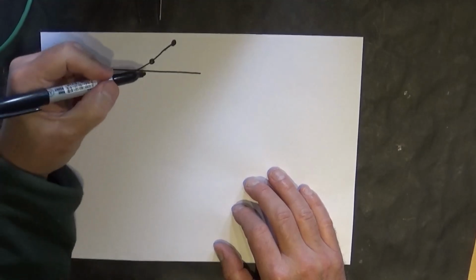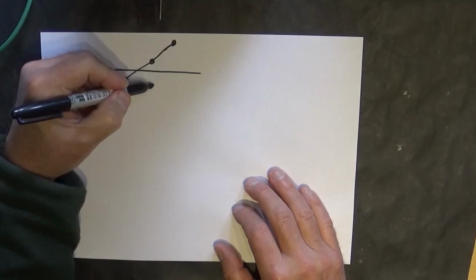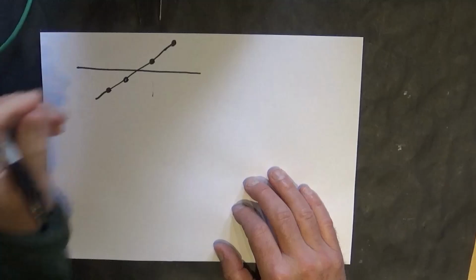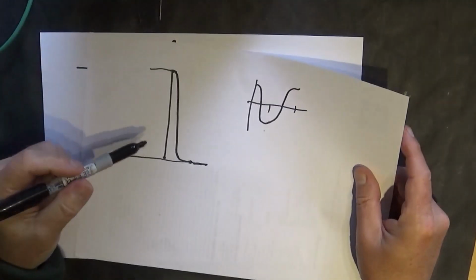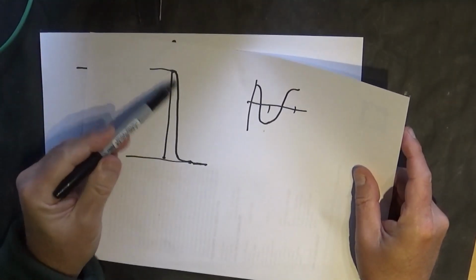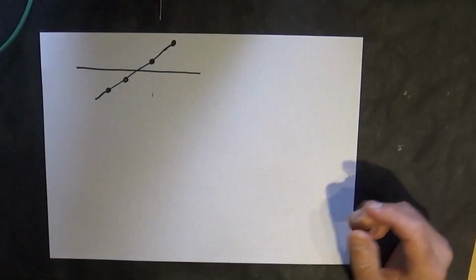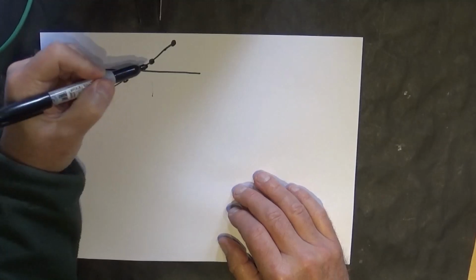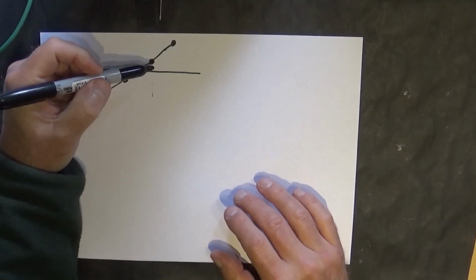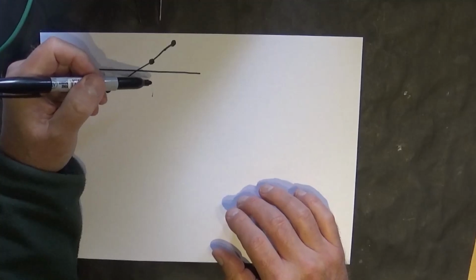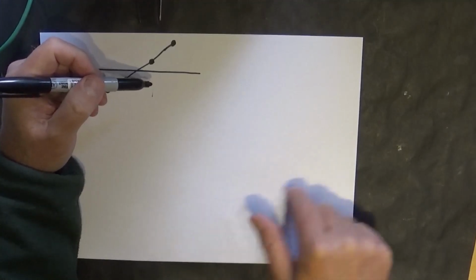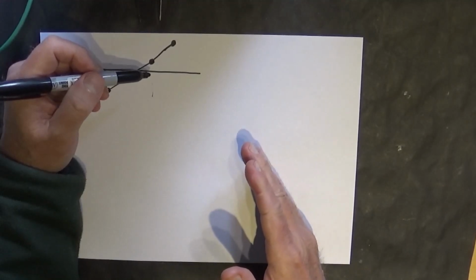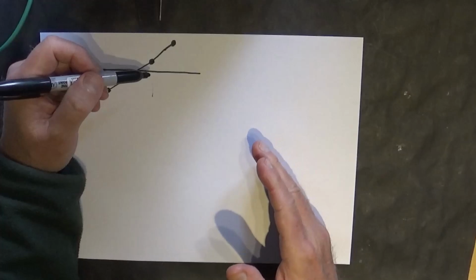So it will start to trigger here, even if we drew a nice, digital friendly curve, it will always start to trigger at a sample. So every cycle of our waveform will be a whole number of samples long. So that's what the stepping is. It's going from, say, 20 samples to 21 samples.